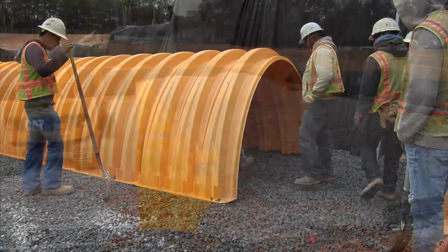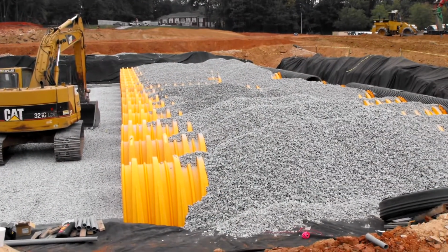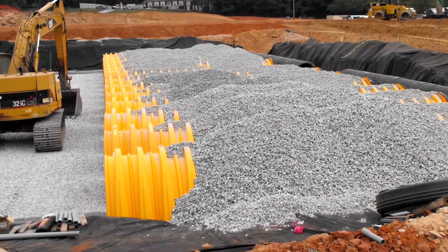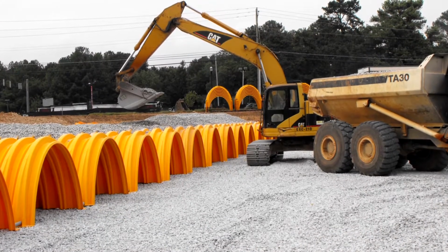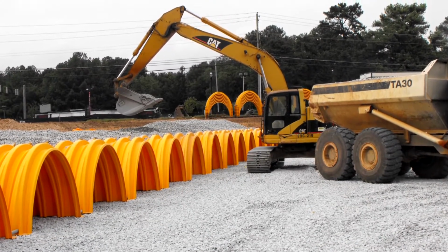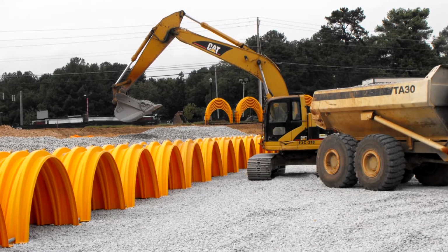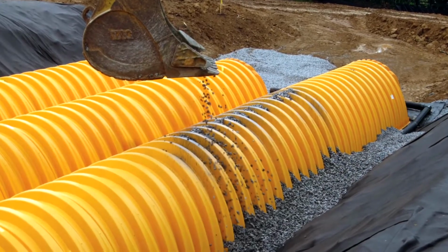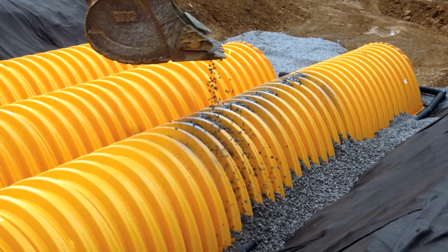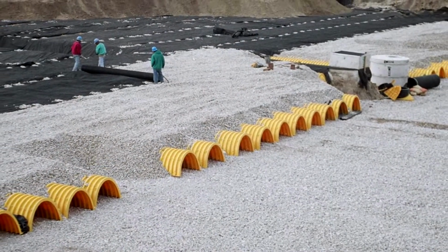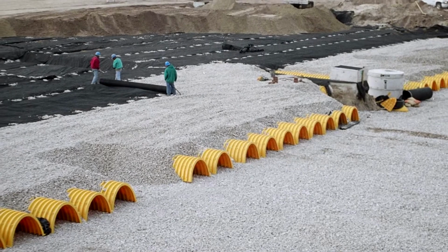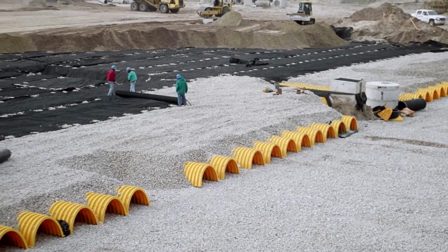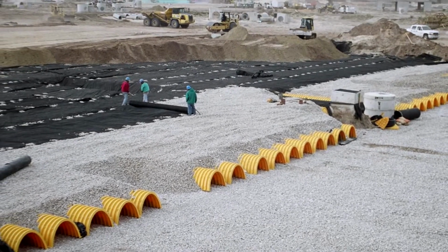With the backhoe situated on the foundation stone or bottom of the excavation, align the bucket so that it is parallel to the chamber rows, and place the embedment stone onto the crown of the chambers so that the stone falls evenly on both sides of the chamber. It is important not to allow the embedment stone to encroach on the joint to be overlapped, as this will prevent the joint from seating properly.